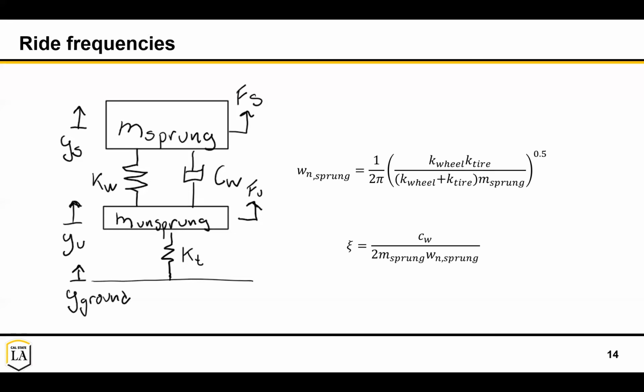Keep in mind, you don't necessarily need these to be linear, but typically for dynamic systems, you want the damping ratio to be less than 1, which means it's underdamped, usually in the 0.7 range, so you get good control but fast dynamics. You can confirm this with tuning and more detailed models, but just to get you in the ballpark of what some of these numbers you'd be looking for are.